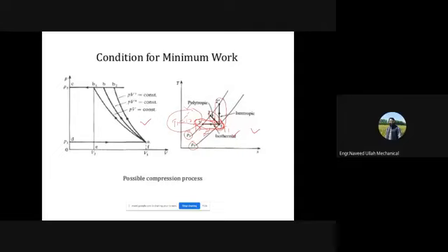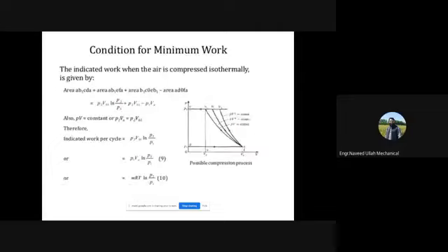Because if you remember, I used to tell you that when the pressure increases in the compressor, an undue temperature rise also occurs. That undue rise we are actually restraining, or restricting, over here. Because of this, the work consumption that goes into friction and increases the temperature, that friction work gets minimized, right.